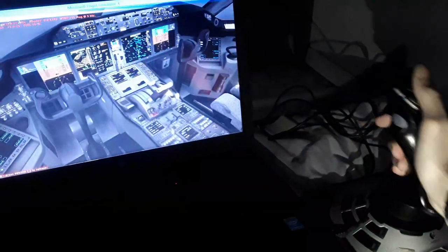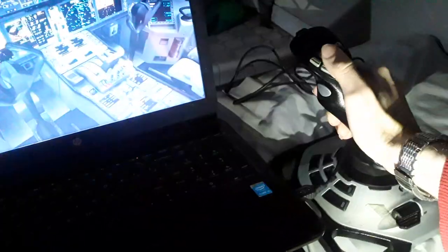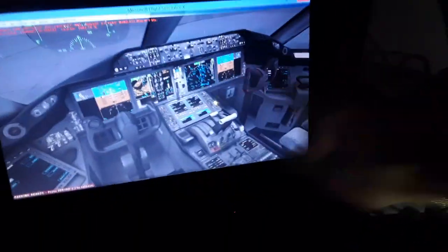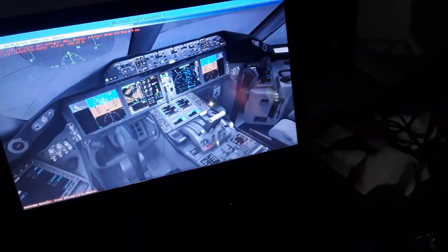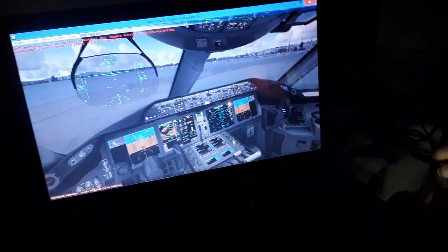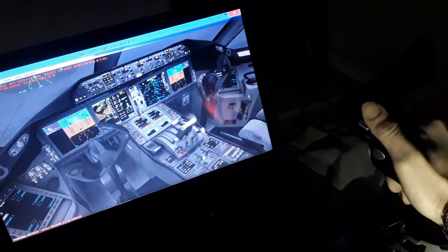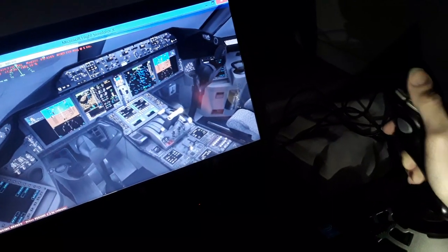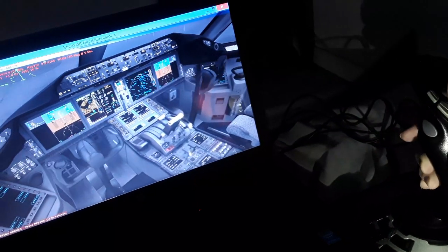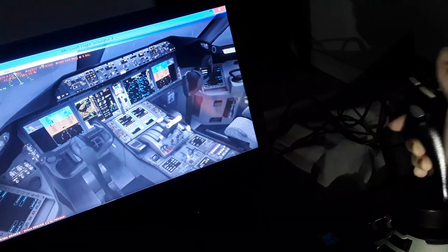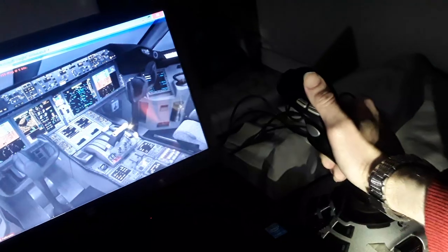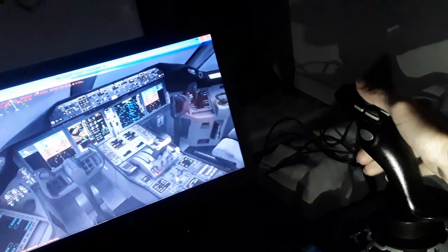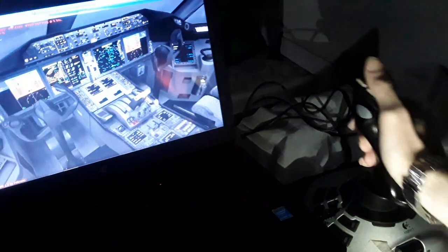So I'll show you how to use the Boeing 787 flight controls for climb and descent. You can see we use the vertical column. It's for climb and for descent, for moving the elevator up and down. We have free movement. Both sides are interconnected, the captain and the first officer. They don't move independently of each other. They move together, all flight controls. So both yoke, rudder pedals and control wheel and control column. So you can see we can use them to change the direction of the aircraft in flight.